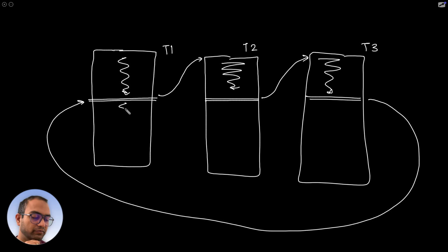It picks up from where it left off, then runs this for some time again, and then pauses and goes back and continues task T2, and so on and so forth. And it keeps on doing this until the tasks exit. Or you can imagine that this can be a while one loop, this can be a while one loop, and this can be a while one loop, right? So it never returns. You can imagine that T1, T2, T3, the tasks or the functions, never exit. They just have a while one in them and they go on doing something in repeat forever.